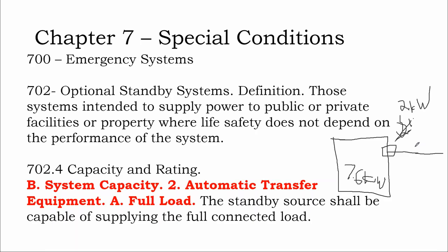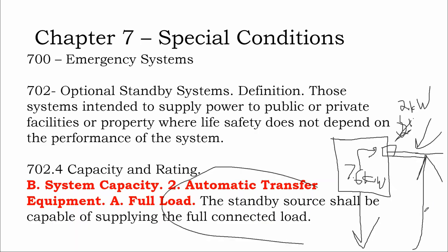Or like with the Tesla Powerwall, the power goes out, and the Powerwall doesn't back up your entire house through its output. It has a critical load side that gets transferred and runs critical loads. And why is that? Because whatever loads are connected to the critical load side, code says you have to be able to power them.